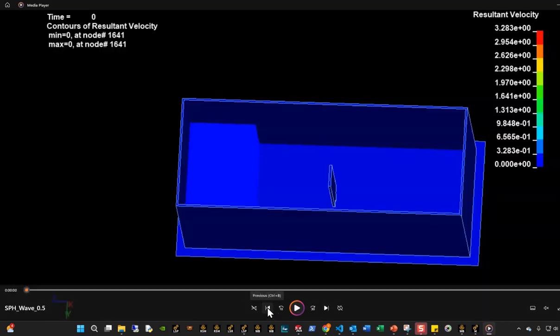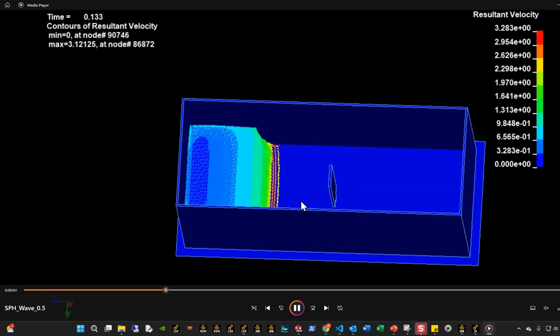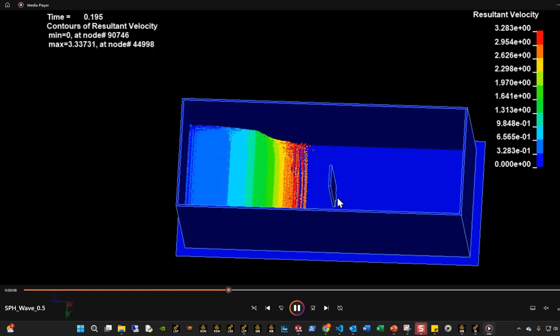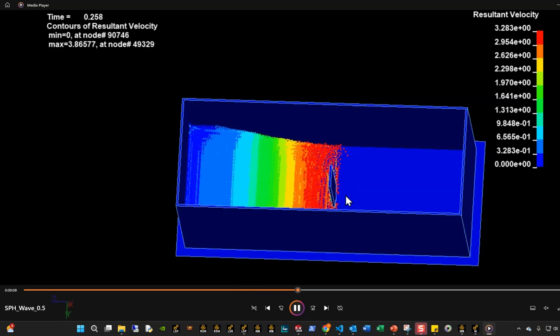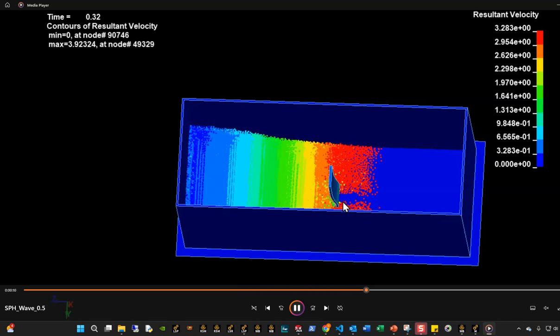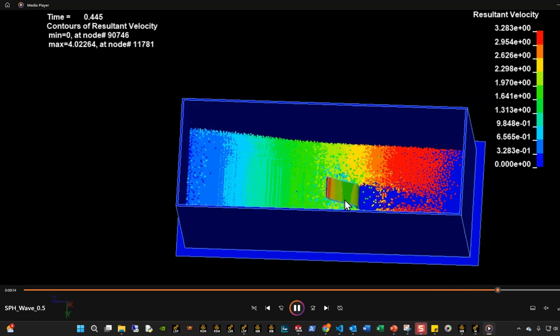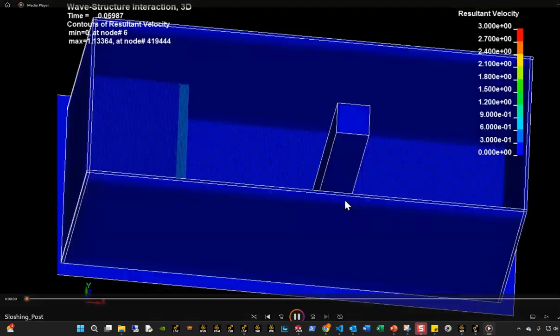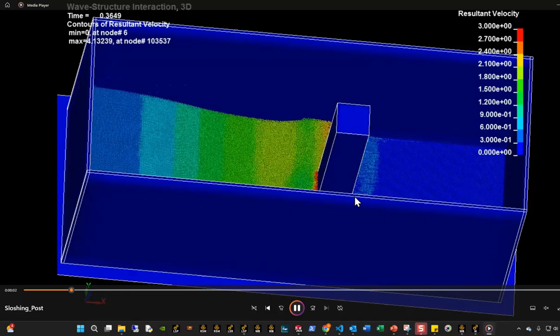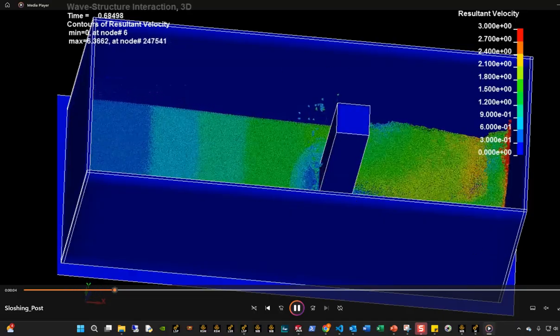where the post itself will actually deform by quite a lot, and that's gonna look like something like this, where the wave is going to flow in and it's going to hit against something very soft, and that's going to generate a deformation. Load is going to be transferred to the structure, and it's going to deform the structure that way. So it's a sort of a Lagrangian method based fluid structure interaction analysis. Okay, and these are the quick results I'm going to show.